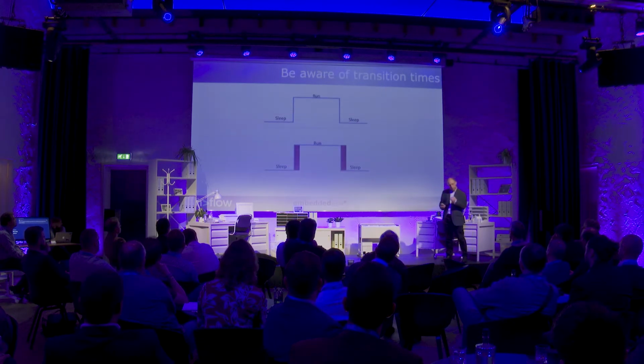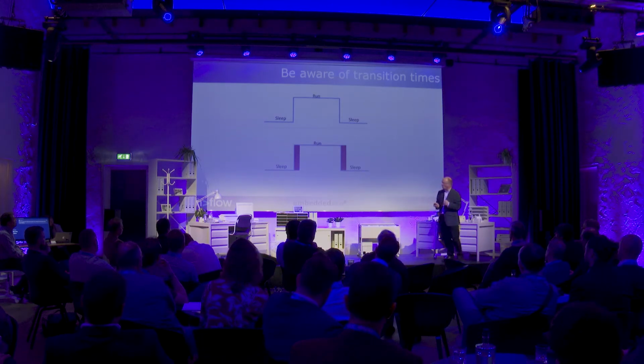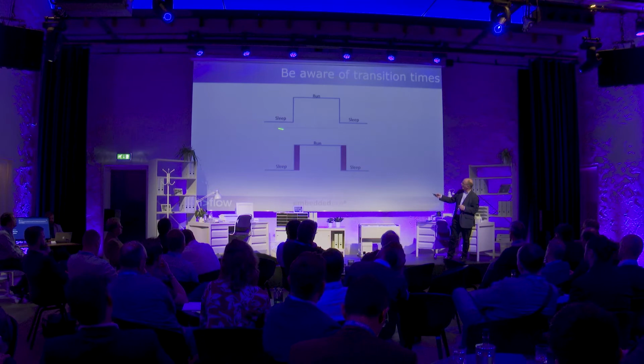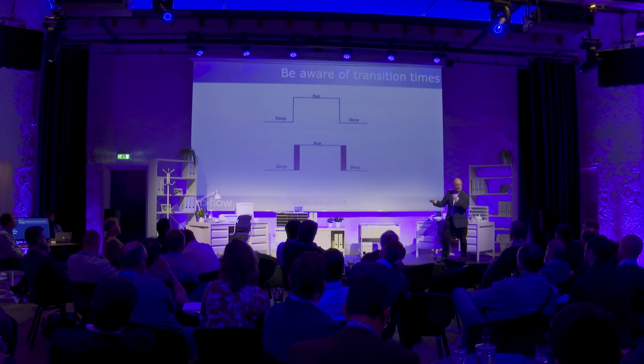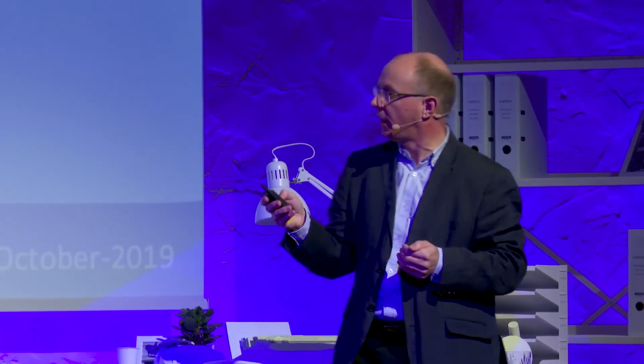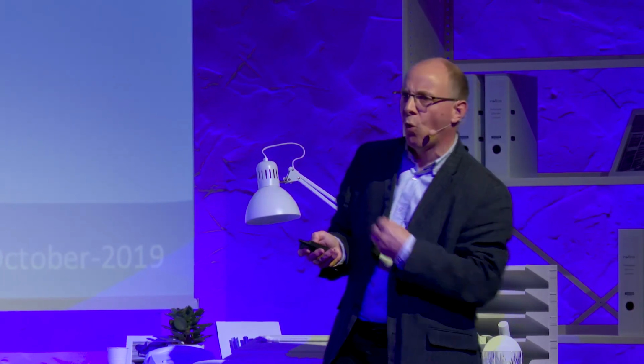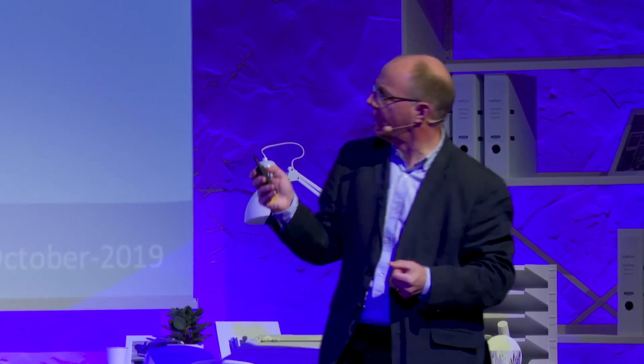One problem that's often overlooked is the transition current. So we're in a sleep mode, and we want to transition into run. In our mind, we think that takes zero seconds. But actually, probably there's no oscillator running in this mode, and to get the chip up and running requires an oscillator to start up and generate some clocks to transition the logic into run. And this adds a hidden penalty, which is not always obvious. So having a grasp of that is very useful.